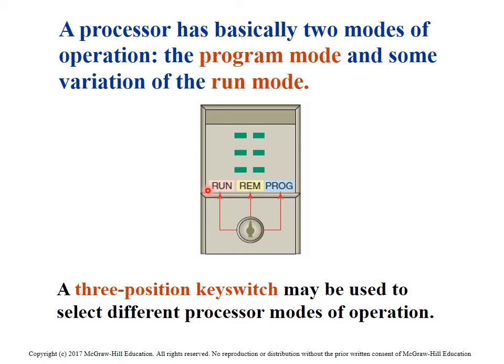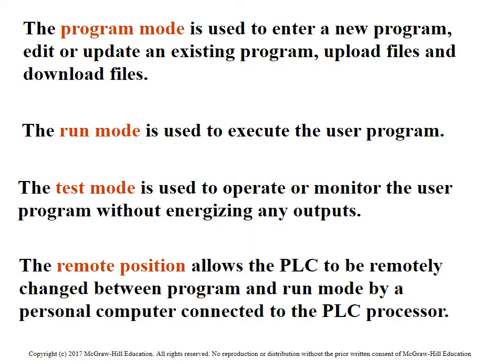It's been my experience, most processors are always left in remote run mode. That gives you the most flexibility and the ability to get in there and edit the program while the process is running, so you can monitor it, you can edit it, and get things back online when need be. So here's some program mode, which kind of reiterates what I just stated. Test mode, they do have what they call a test mode as well. That allows you to make online edits. Typically in 164 we don't do any online editing. We save that for 166.